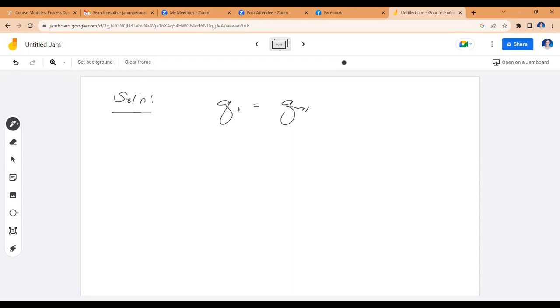However, oil is going to reject heat, so this Q will be negative. We cannot equate it directly to Q of water because this one is negative. So in terms of magnitude, for them to be equal, you just place a negative sign in here. Failing to place a negative sign before the Q of the oil will give you a very wrong answer, because in this case you are equating the magnitudes only, so it has to be all positive. So I'll place here negative of the oil.